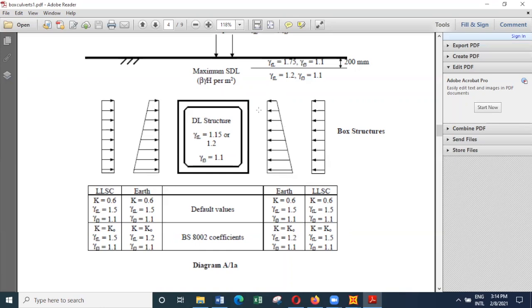So you can get the forces acting from both sides and forces from above. So you can create the load combinations. And then the next important question that you can ask is, how you are going to deal with the foundation. And we can actually deal with the foundation by considering that it is all going to be on springs. And we can actually apply a set of springs here and then do the analysis.